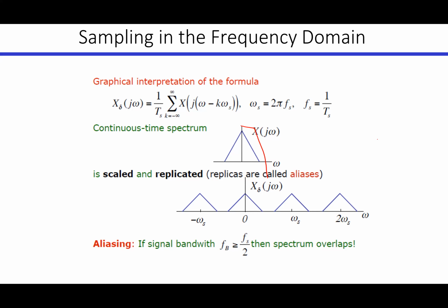Yes, Hamza. Will this anti-aliasing filter be somewhat working as a low pass filter, right? Yes. Now, we will see after a while that my original signal can be a band pass signal. It's not a baseband signal. So in that case, you will need a different type of filter as the anti-aliasing filter. Okay.